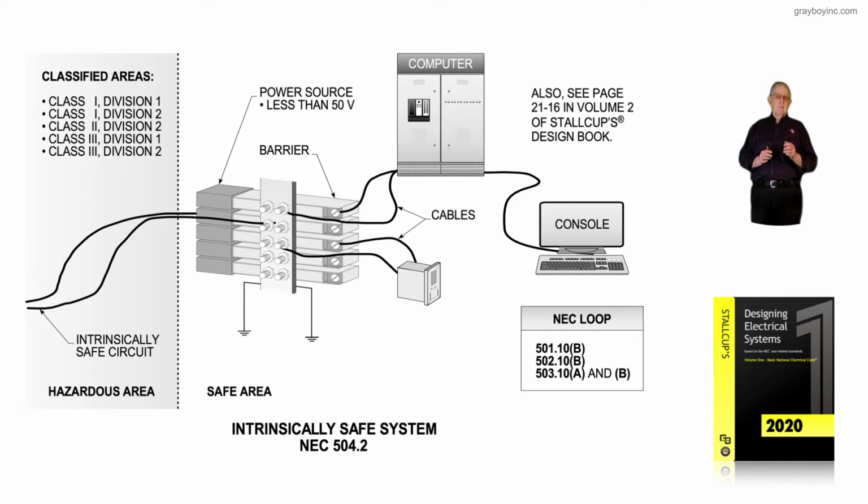They're recognized in NFPA 497, where designers will pick up, say, the flash point of a liquid or gas, the ignition temperature, the lower and upper flammable limits, the density, does it rise or settle? The only place we can pick that information up is in NFPA 497 to start with.